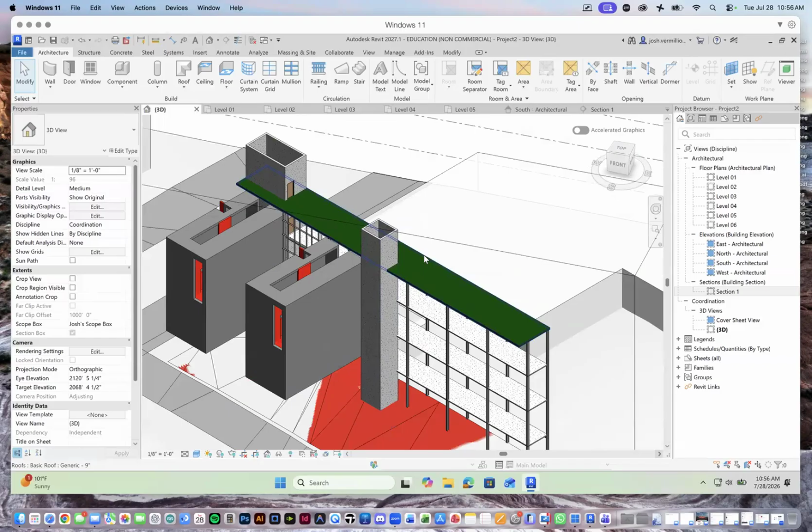So for instance, if anybody needs to get on your roof, you have two options. One is that they have a temporary thing and they have to rappel down to it or whatever, which gets kind of crappy and chintzy. But oftentimes you'll see that the stairs and elevators just serve the roof. So if I was a repair person having to put a patch on the roof or something, I might take the elevator up to this, get out, and then if I needed to get out in an emergency, I have two means of egress, two stair towers on either end, like a dumbbell, basically. Okay.